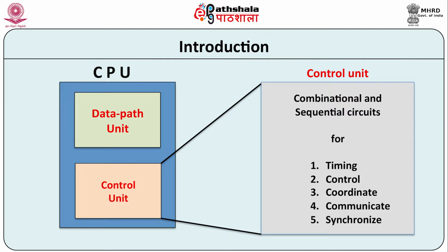The instruction fetched from the memory and stored in the instruction register is fed to the control unit, and appropriate control signals are generated by it to execute that instruction. These control signals are fed to various parts of the data path as their control signals. For example, the ALU needs the ALU function code, and the multiplexer requires select lines, etc.